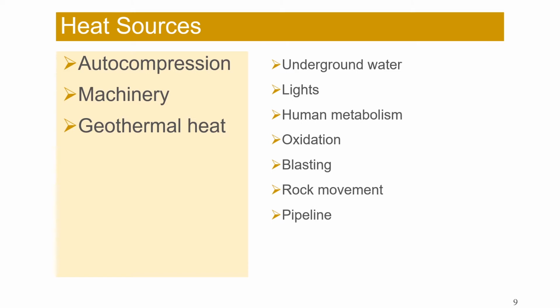Heat is emitted into subsurface ventilation systems from a variety of sources. In most coal mines, the airstream itself is sufficient to remove the heat that it produces. In deep metal mines, heat is usually a dominant problem and may necessitate the use of refrigeration plant. Conversely, in cold climates, the intake air may require artificial heating in order to create conditions that are tolerable for